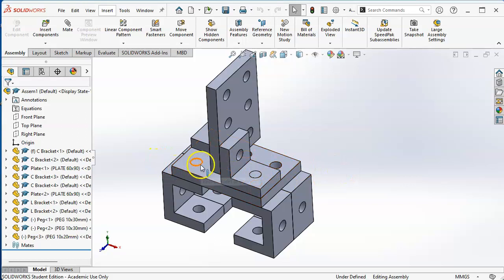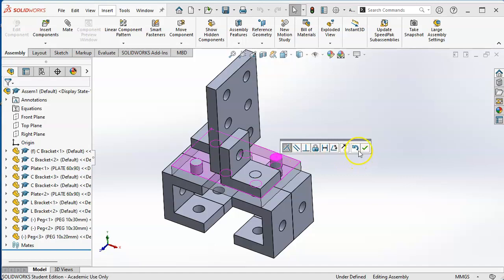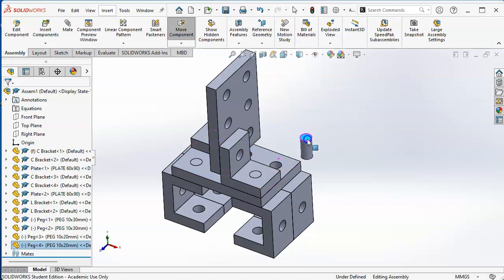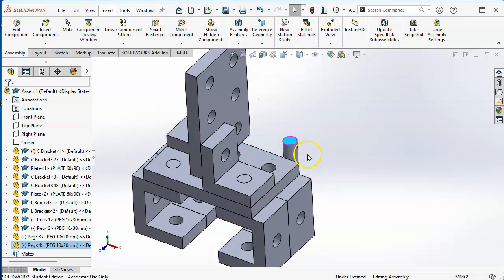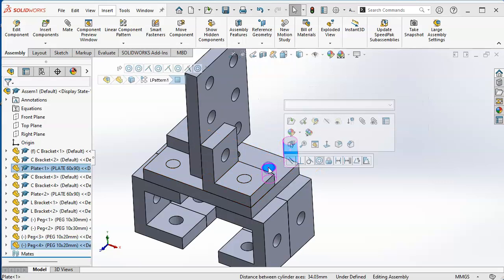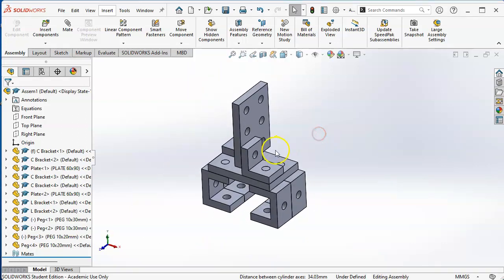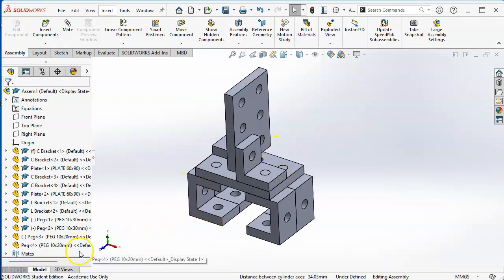All right, so the rest of these are going to be 10 by 20. So control button, left click, make sure I'm saying this right. We drag to. Now that one picked up the coincidence. I noticed it did this on 5.5. If I reverse and then go ahead and hit OK, well, I can still see the top. It may take a couple times to select it, but I'll go in and do the concentric, and then on that one I'll lock the rotation. So kind of a toss-up. Like I said, I'm not sure.